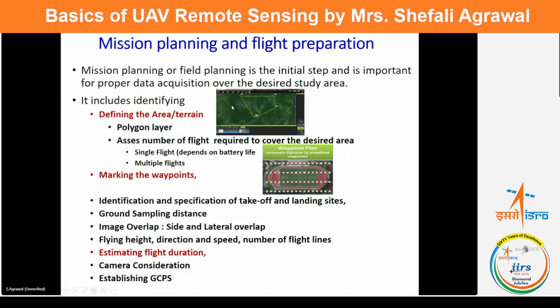Accordingly, if you have an onboard GPS for georeferencing, it's okay. Else you need to plan on the ground to collect GPS GCP data sets simultaneously, to decide where to keep these ground control points so that they can be utilized effectively for georeferencing and correcting your data sets.